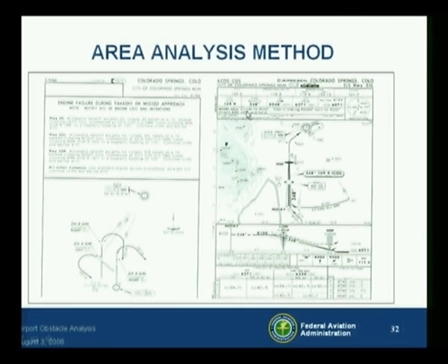The missed approach says climb to 8,000 feet, then a climbing right turn to 9,000 feet, direct the Black Forest VOR and hold. So you basically head up toward the rocks north of Colorado Springs, and you enter the hold up here. Well, if you experience an engine loss going into Colorado Springs, you probably are going to have a difficult time this close gaining 3,000 feet in altitude and getting into the holding pattern.